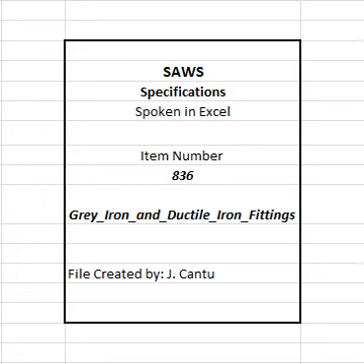2. Approved adapters shall be used where necessary to provide a transition between pipes and/or fittings of differing outside diameters. 3. Thrust blocking shall only be utilized, in addition to restraining glands, if specified in the contract documents, when tying into existing non-restrained pipe, or when approved by the inspector. 4. Anti-corrosion protection consisting of polyethylene sleeve and asphaltic material for ferrous surfaces shall be applied to exterior surfaces of all fittings installed. Anti-corrosion embedment shall be provided as specified in specification Item number 804, Excavation, Trenching and Backfill.